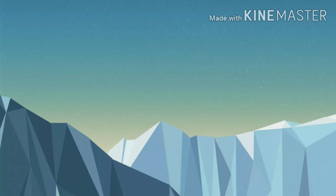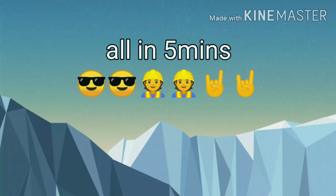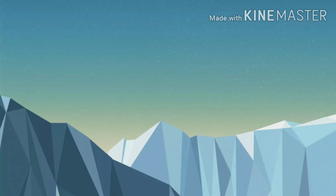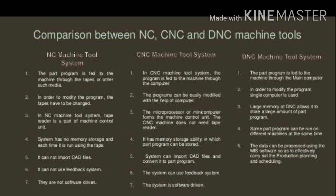With this, guys, we are completing our session of numerical control, CNC and DNC machine. So lastly, guys, let's see this full session in 5 minutes with the help of the comparison between NC, CNC and DNC machine. In the numerical control system, the part program is fed into the machine with the help of punch tapes, whereas in CNC machine the part program is fed into the machine with the help of the keyboard, whereas in DNC machine, the part program is fed into the central computer instead of feeding the part program in a separate machine computer.